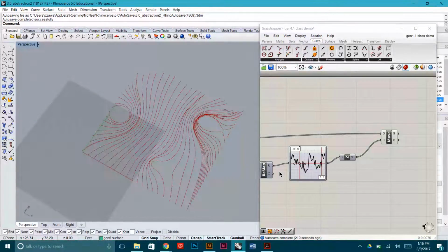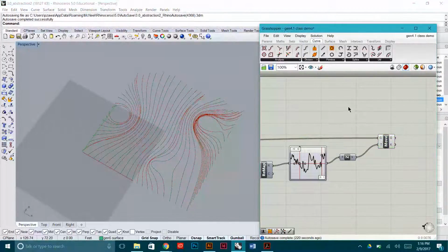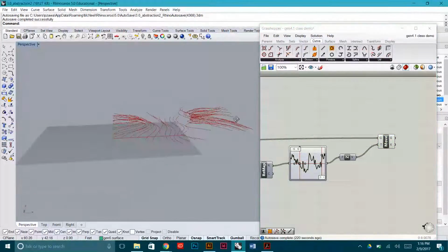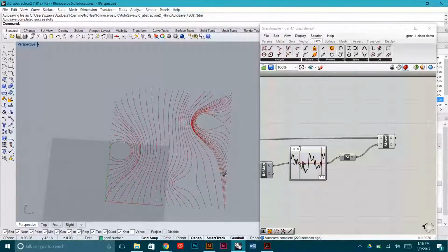You just create it from the contours instead of multiple. Say what again? Create surface from contour. You could, I guess. I've never tried that. I mean, that's essentially the same thing. Are you thinking of using a patch or something? Exactly. Drape. I'm never a fan of the drape tool. I don't know why. Does it lose too much resolution for you? Yeah. But it's quick and easy, and it's a usable surface.